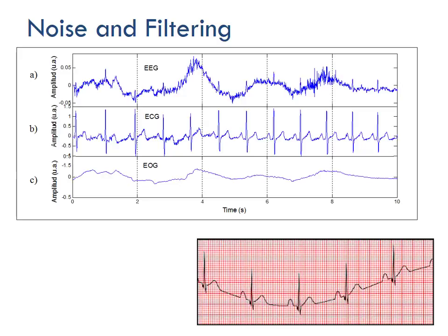If you're wearing an EEG to measure your brain waves and you start twitching your muscles or moving your face muscles, that can really throw the EEG off, because your facial muscles and your scalp muscles overpower the EEG signal. Again, muscle is a great natural amplifier.